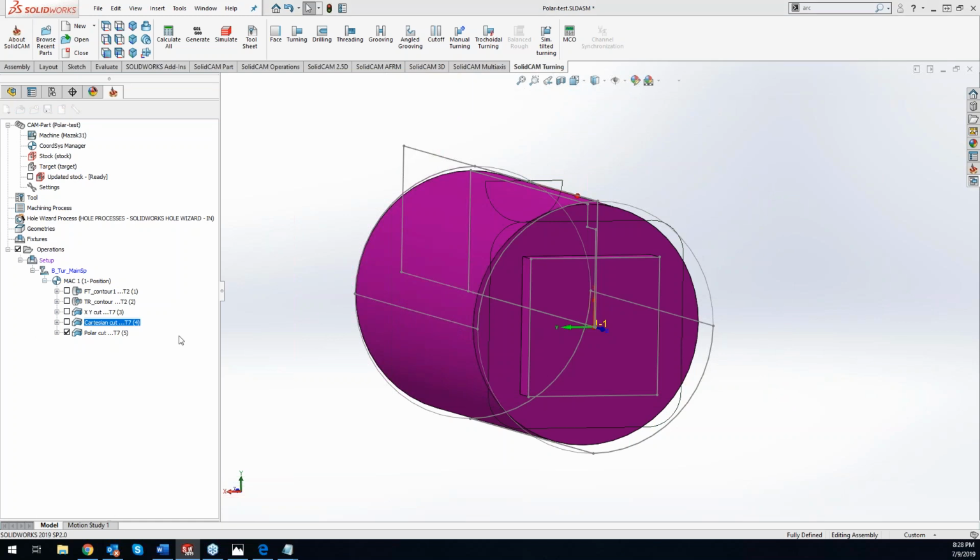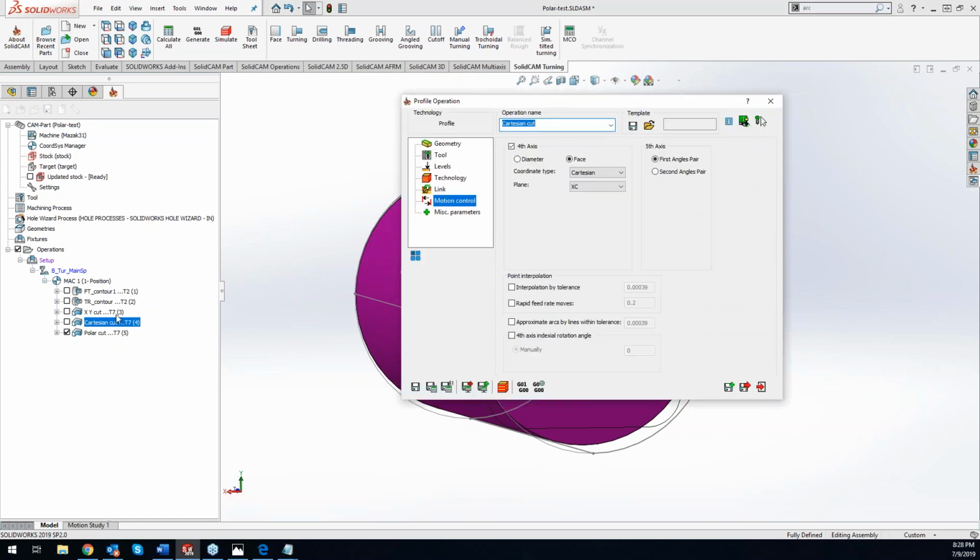The only one that you're going to see that's different would be the XY planar cut, which should have the C-axis locked, as opposed to the rotary movement, which will show the Y-axis essentially fixed and the X and C-axis moving in conjunction with each other. Great question, Scott. Any other questions, guys?